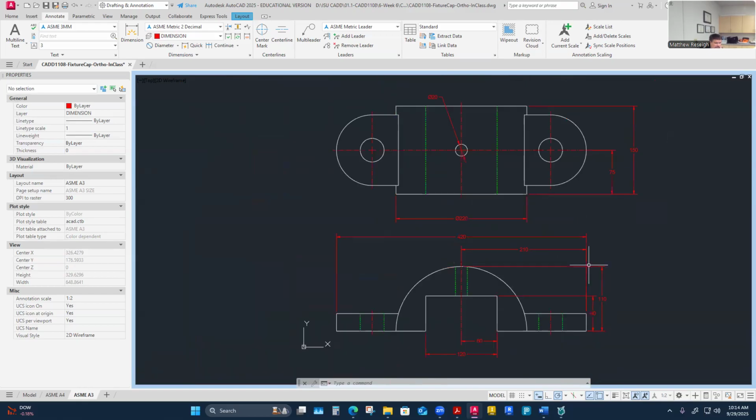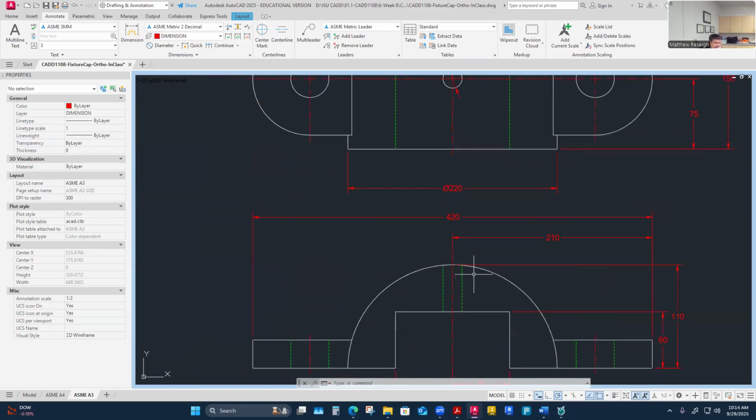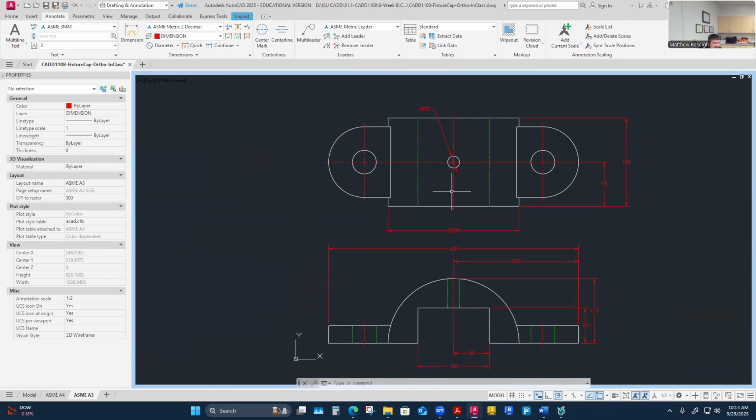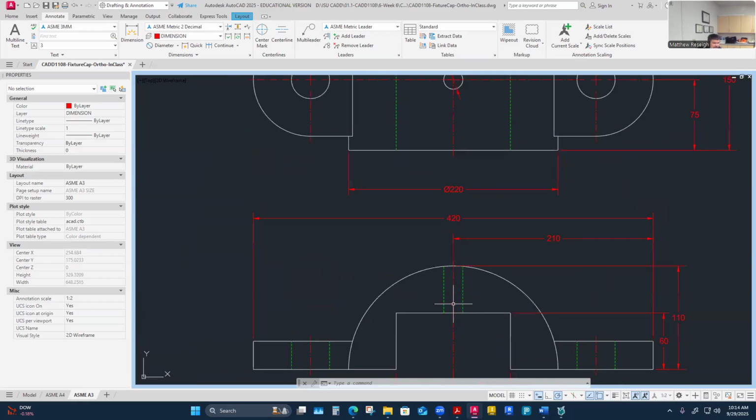I know it's pulling from this datum over here. So you can think of 210 as being kind of a dual dimension, but maybe it's more critical that it's just shown to be center as the location. Either way, I've got a linear measurement associated with it. It's arguable whether that's totally needed because I'm using that right side surface, which I've already discussed is not a great datum point, but I'm kind of using it.